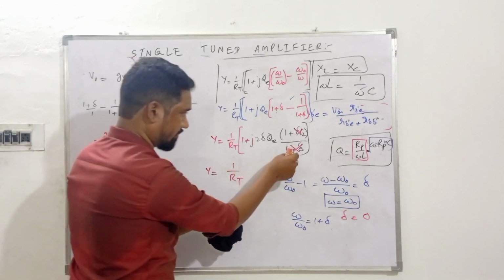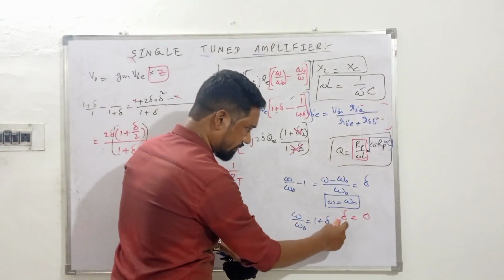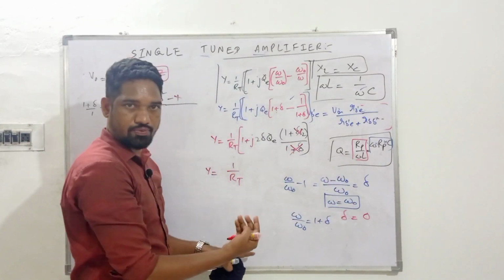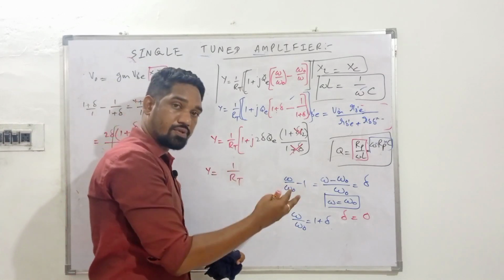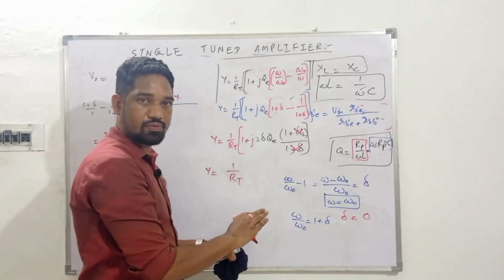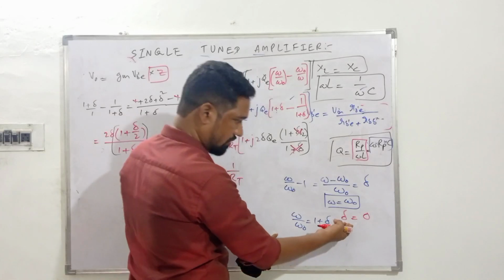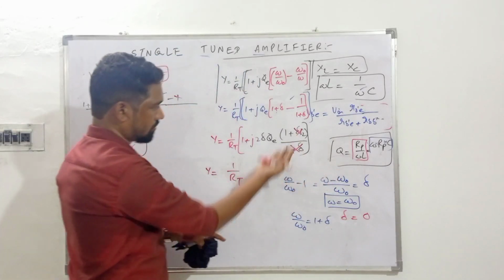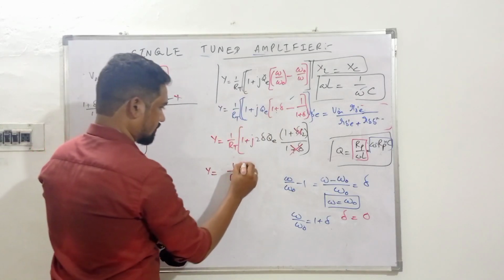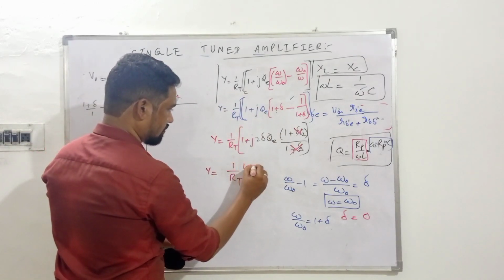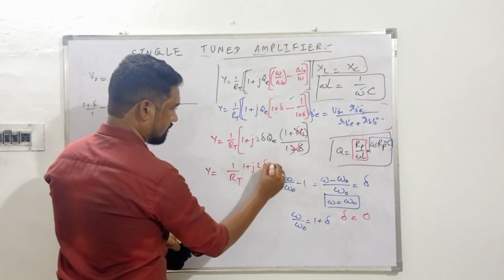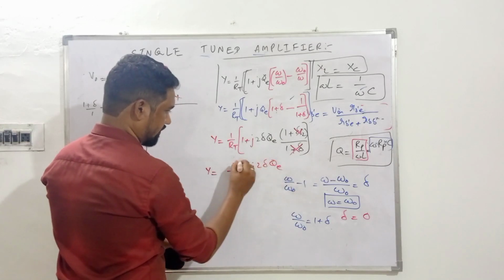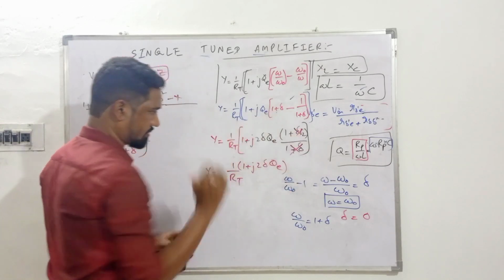Go back to that statement. Okay, so at resonance frequency, del equal to 0, it's very much proved. So for frequencies around the resonance, we'll have a smaller value of del. If del is small, half of del will be even smaller, so that can be neglected. Okay, so here 1 plus j 2 times del Q effective will be left over, neglecting this one.